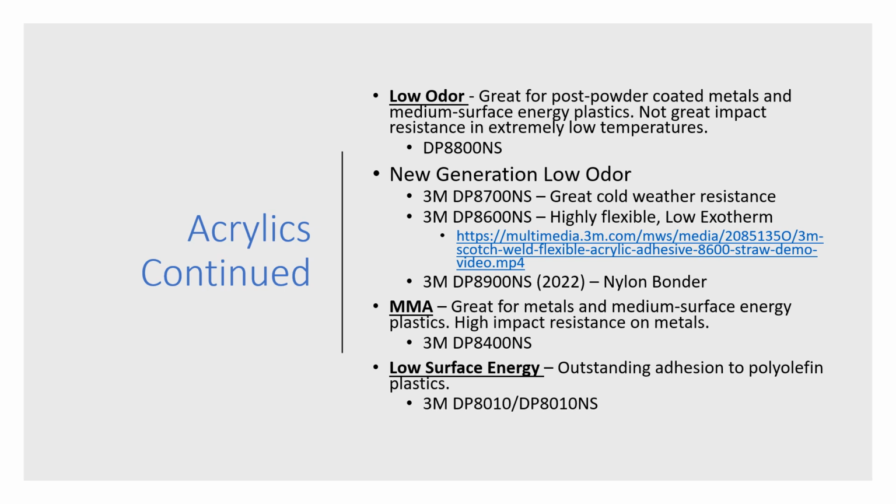The 05, the 10, and the 25 stand for the open time. What the open time means is the time you have after you lay the bead of adhesive before you have to make the bond. And then with structural adhesives, there is time to handling strength. That is the time it takes to reach handling strength, which is defined as 50 psi in overlap shear. So this is your fixture time: the time it takes for the adhesive to set up enough that you can move it down to the next step in the production process.